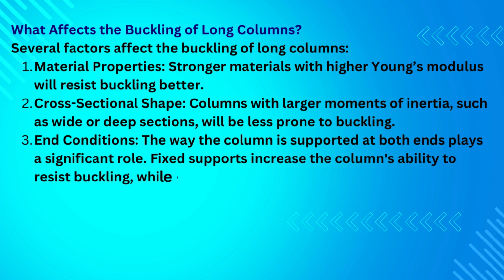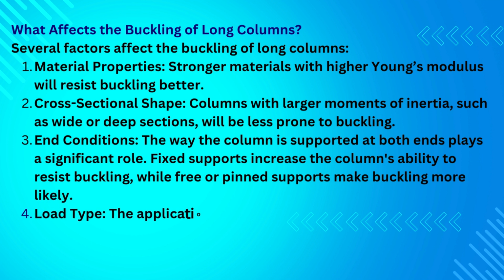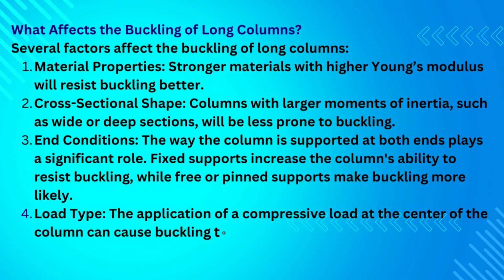Fixed supports increase the column's ability to resist buckling, while free or pin supports make buckling more likely. 4. Load type. The application of a compressive load at the center of the column can cause buckling to occur more easily in long columns.